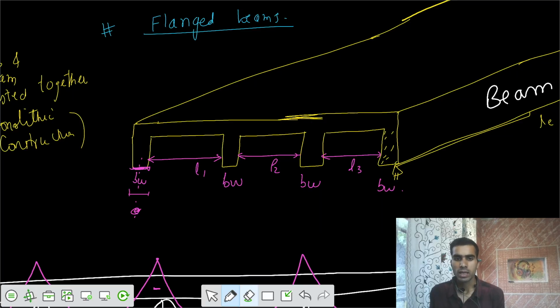I'm going to say that the total loads on the slab would be distributed on these different beams. If we talk about a particular beam, let's say this one, number one, a part of the slab from the left side and a part of the slab from the right side of this particular beam one, that total load would be transferred entirely to this beam.